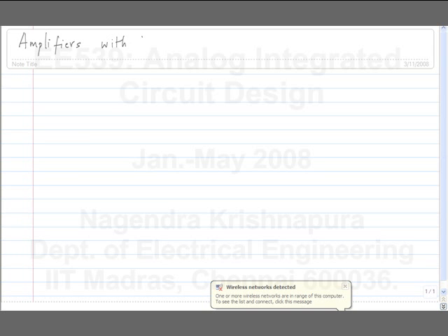So these are amplifiers using transistors which are biased at a given current I0. We have already seen how to bias transistors at a given voltage and make amplifiers. That was the first thing we started off with. But then we argued, we reasoned out that biasing at a constant current will make the circuit less sensitive. So we will use that.